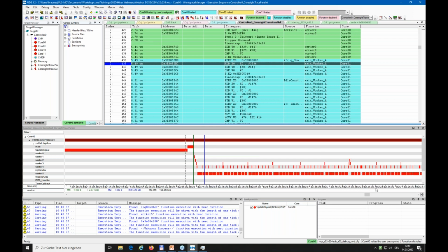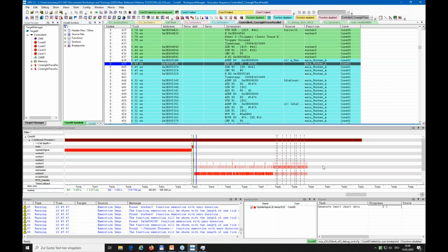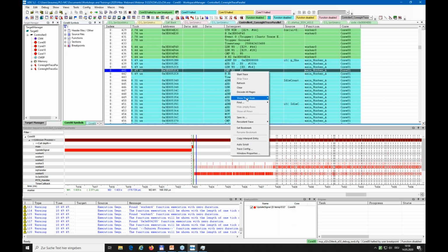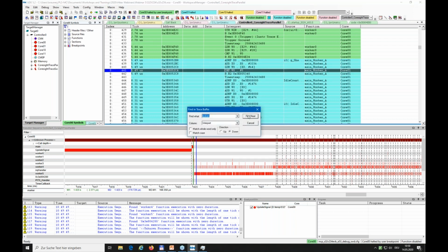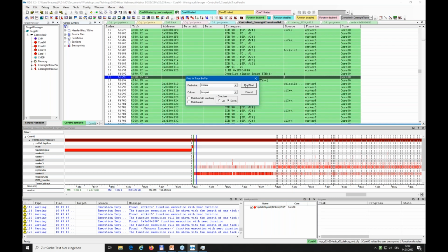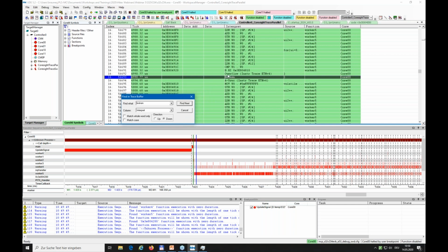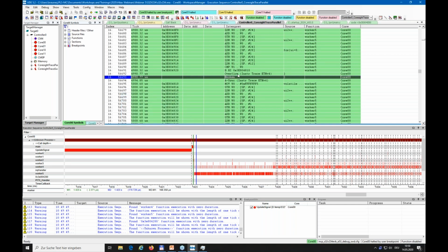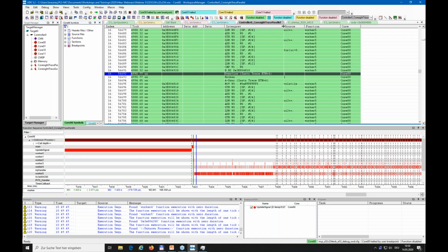What you also see, and that is unfortunately sometimes the case for trace-based debugging or trace-based measurement, is that we have some broken messages in between. These are the gray dotted lines here. And if you look for a broken message here, yeah, I did that before, so it is already filled. Then you see a broken message caused by an overflow of the trace system.